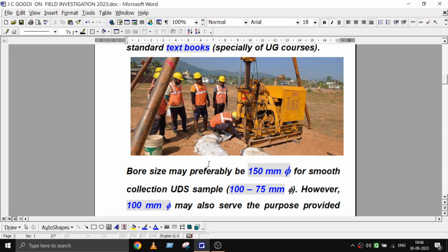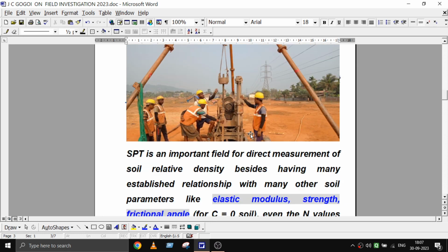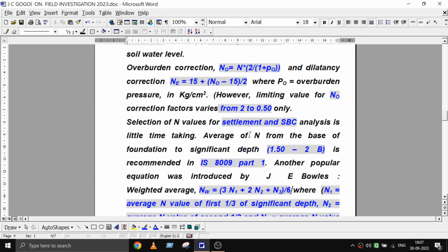After that, we should gently pull it out, maintaining the water level at ground level. If we do not maintain the water level, there will be some hydrostatic pressure difference, so it may not come up. Collection should be very careful.